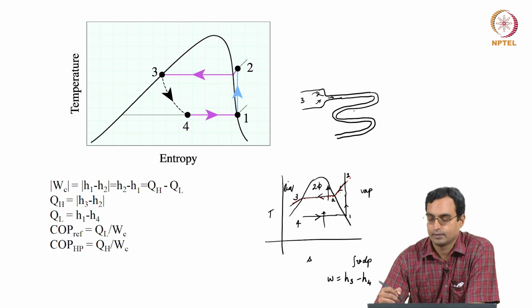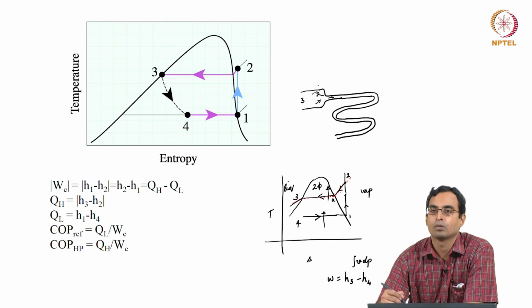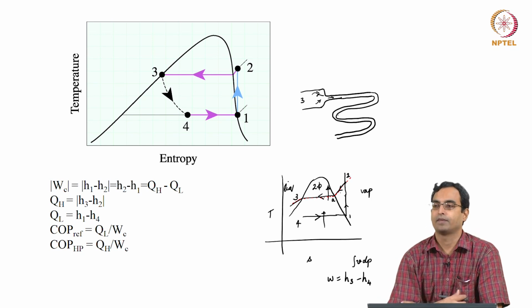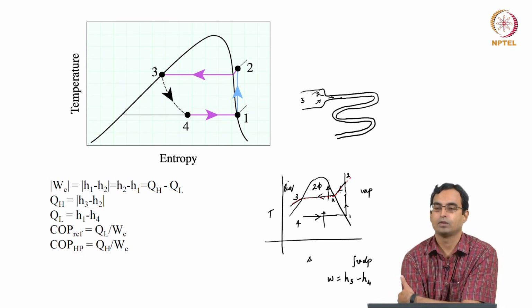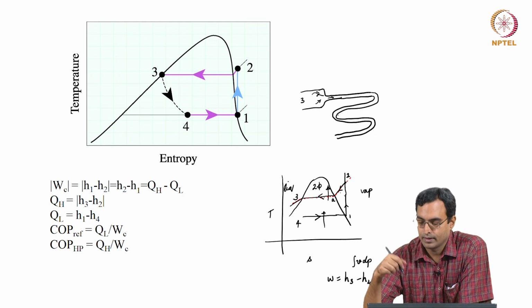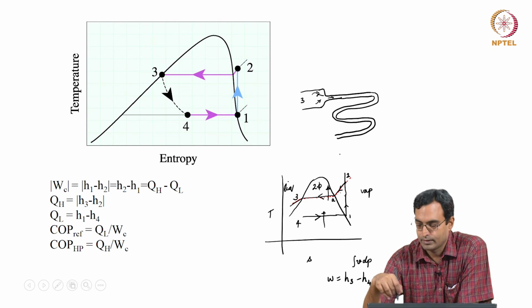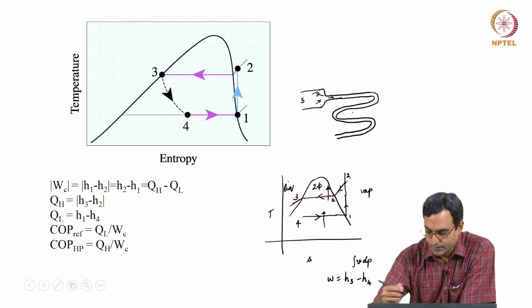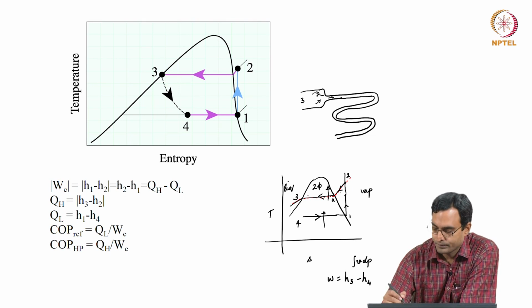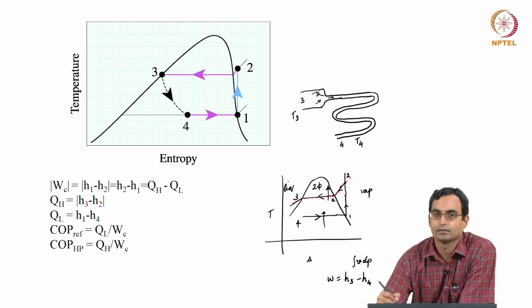And for non-ideal gas substances, if you choose the range of initial temperatures correctly, what you would have is usually a temperature drop. Of course, the actual case of whether the temperature will drop or increase depends on the Joule-Thomson coefficient, but if you are looking at a gas, it could either increase or reduce. In the case of these kind of mixtures, in the case of liquids of the kind we have here, in this condition the temperature would drop as the pressure drops. So, at 3 the temperature is T3, at the exit of this at 4 the temperature drops from T3 to T4.